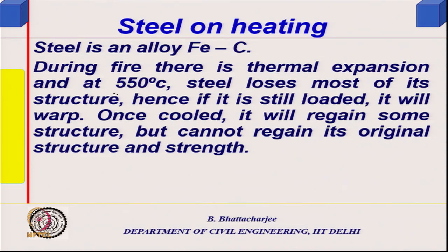There is thermal expansion up to 550 degrees, and at 550 degrees centigrade, steel loses most of its structure responsible for strength, etc. So, if it is loaded, it starts warping, it will warp. Once cooled, it will regain some structure, but cannot regain the original structure and strength.